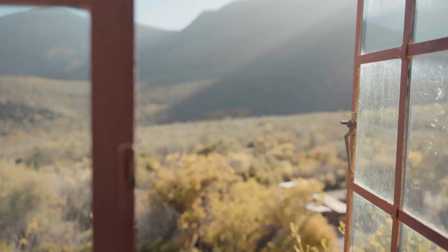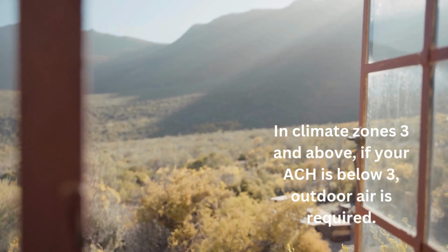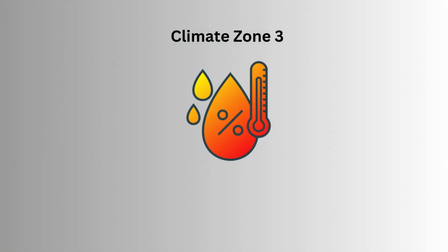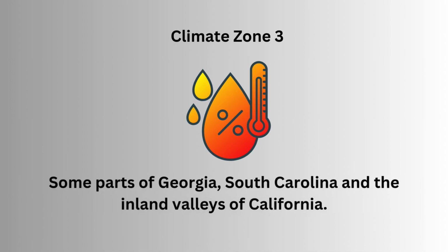For any climate zone from Climate Zone 3 and up, if your air changes per hour are less than 3, you're required to have outdoor air. And although Climate Zone 3 is less extreme than Zones 1 and 2, moisture management is still important. These states include some parts of Georgia, South Carolina, and the inland valleys of California.